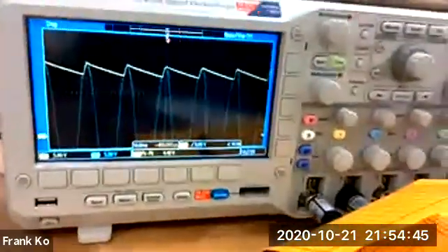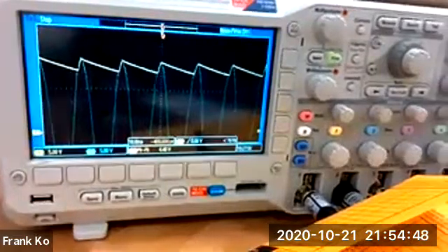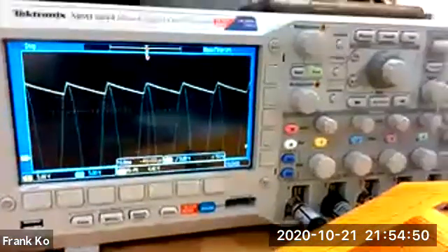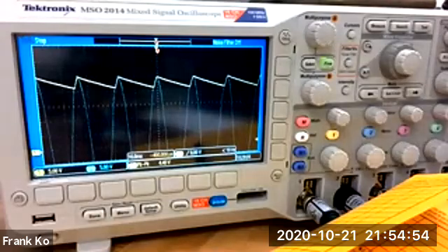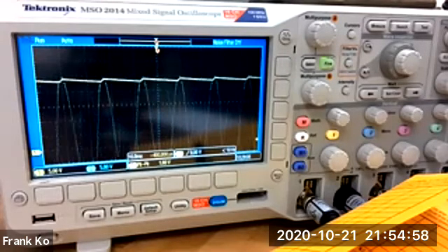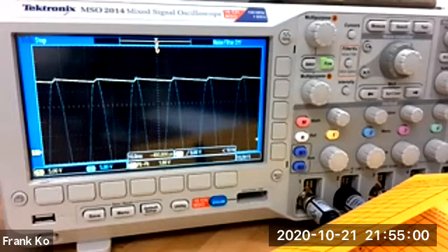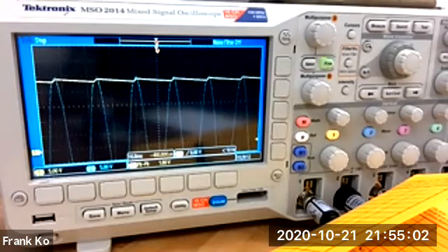As I'm looking at the oscope, the screen was frozen from the 100 microfarad cap. I'm going to put this back in run mode. Watch this in the run and stop. My ripple diminished dramatically. Yes. It's tiny.